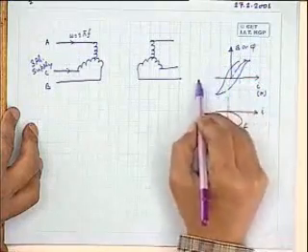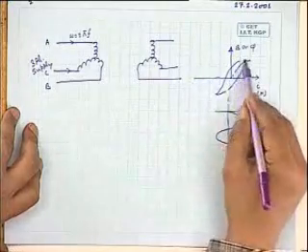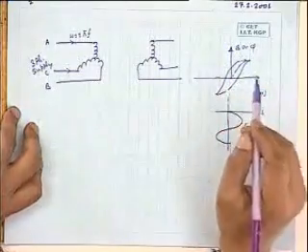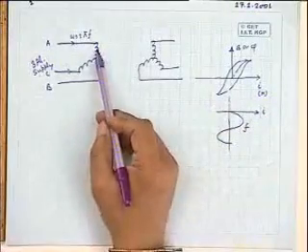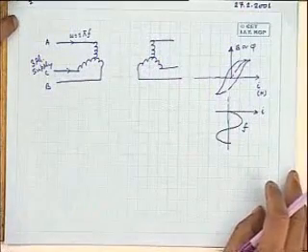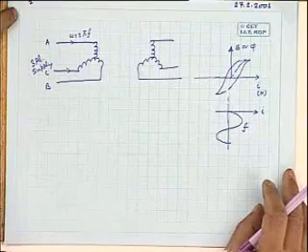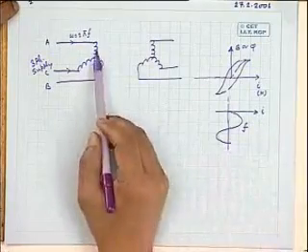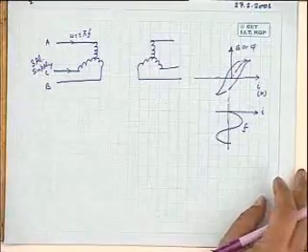But if you go back here, the flux distribution will not be sinusoidal because it is a double valued function in this hysteresis loop, and the nature of the flux distribution will be flat topped, which will make the induced voltage in the various windings distorted. The induced voltage will contain the fundamental frequency and a third harmonic frequency, and it will put additional stress on the insulation of the transformer. Now,